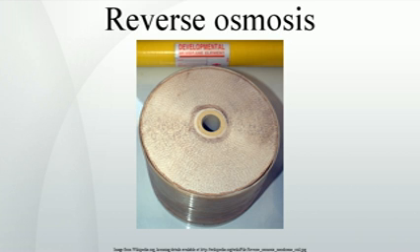Some small-scale desalination units use beach wells. They are usually drilled on the seashore in close vicinity to the ocean. These intake facilities are relatively simple to build and the seawater they collect is pre-treated via slow filtration through the subsurface sand seabed formations in the area of source water extraction. Raw seawater collected using beach wells is often of better quality in terms of solids, silt, oil and grease, natural organic contamination and aquatic microorganisms, compared to open seawater intakes. Sometimes, beach intakes may also yield source water of lower salinity.